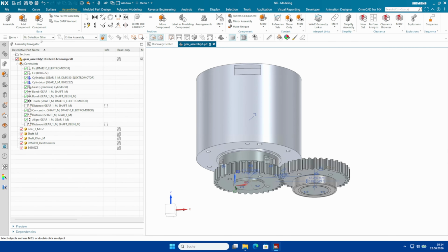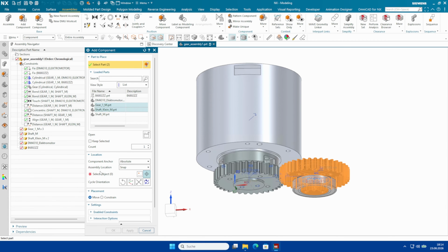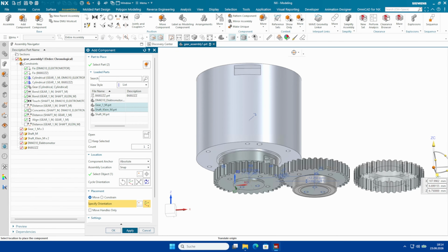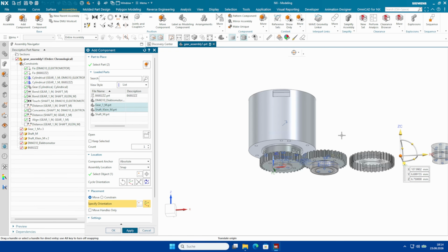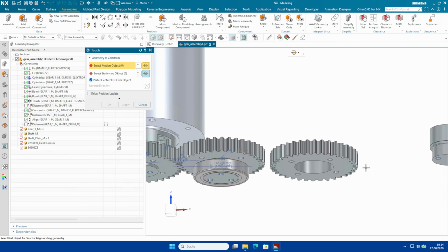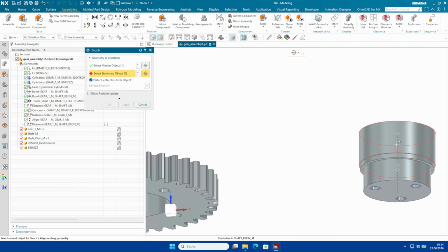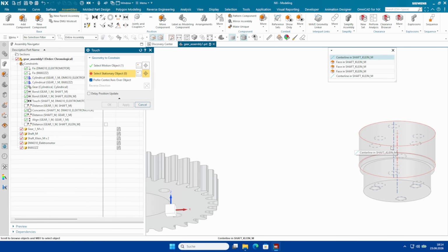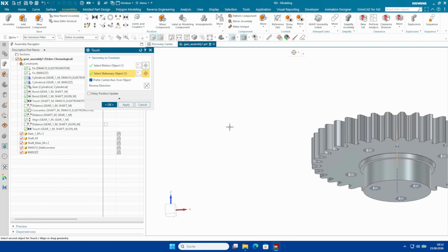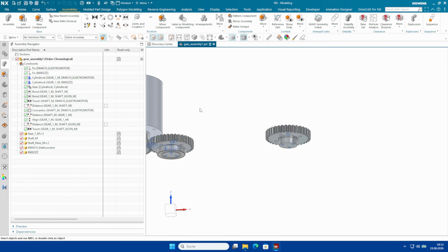You can also go ahead and add a third gear if you would like, and let's say you can just add this, click on OK, try to align their axis. So let's go this and let's use this axis, align shaft. There you go. And if I want to reverse the direction, I do not.